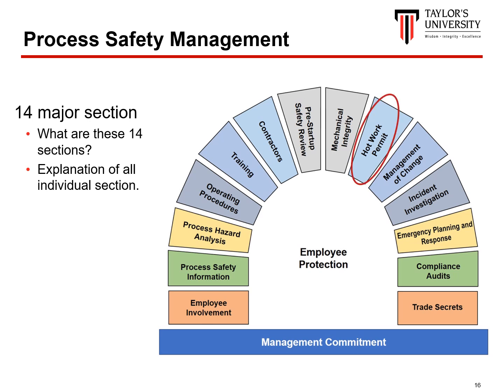The PSM standard ascertains that a system is in place to prepare and issue hot work permits before conducting any hot work activities such as welding, grinding, or using any spark producing equipment. The permit requires the date authorized to work, the equipment involved in the work, a system to maintain the documents of certification, the identification of openings where sparks may drop, the types and numbers of fire extinguishers,